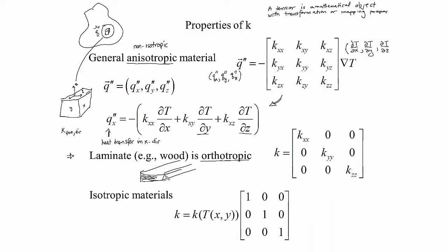So there is a laminate or grain structure that runs in this piece of wood. What that means is that the heat transfer rate in this direction, you might call that, say, the z direction, might be very different from what it is in the y direction. So for a piece of wood, we might expect that depending on where we sit and how we're looking relative to the grain, the orientation matters and the thermal conductivity changes appropriately.